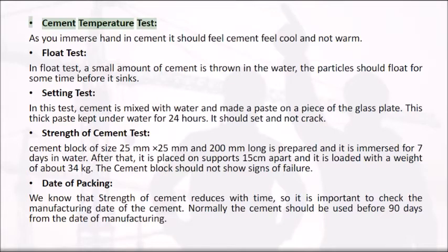Cement temperature test. As you immerse your hand in cement, it should feel cool and not warm. Flow test. In the flow test, a small amount of cement is thrown in the water, and the particles should float for some time before they sink.